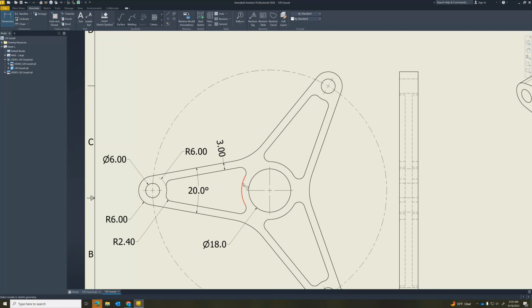I do need the radius or diameter of this circle. And it's getting a little crowded there. You may want to move just to a different one, and so we're not too crowded in any one spot. And we do need the angle between here and here. You can see that there's symmetry, and since there's 3 of them, it would be 120 degrees, but we should really still give that angle.